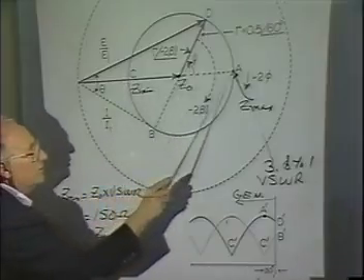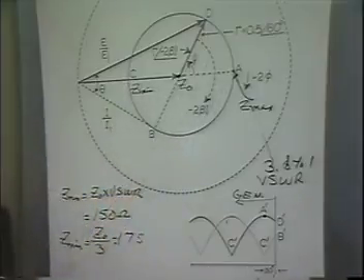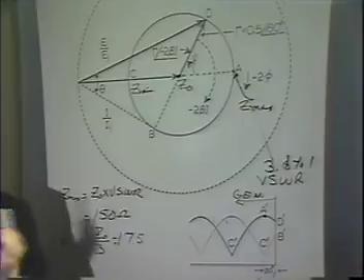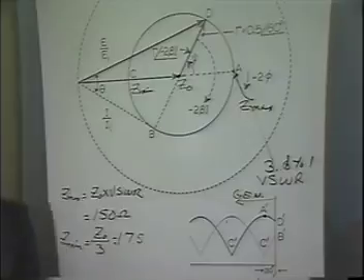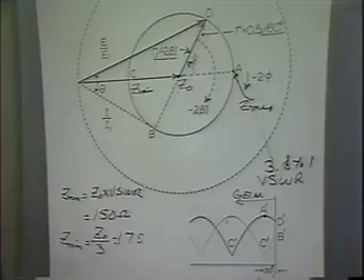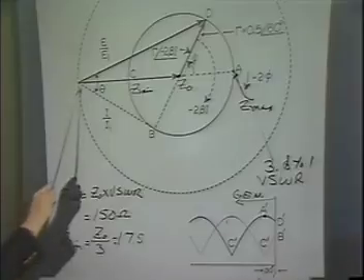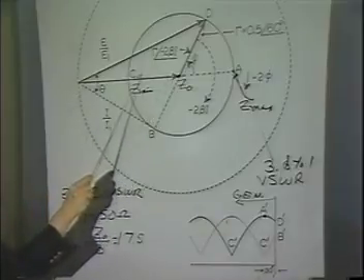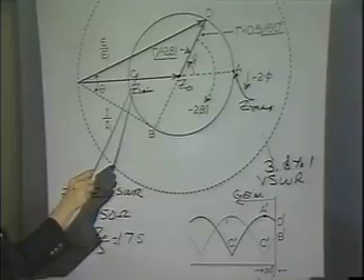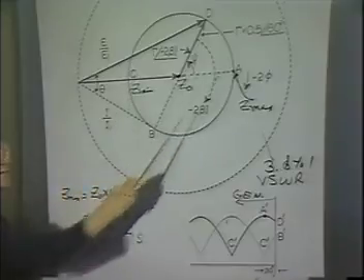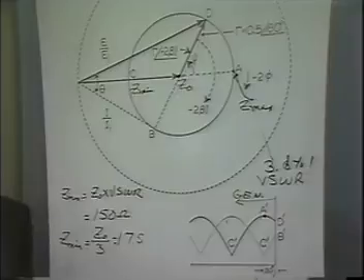Going across the chart over here, Z maximum, pure resistance, greater than Z0. That's the only 2 points on the transmission line then, Z max, Z min, and repeating itself, Z max and Z min. That's the only time you have a pure resistance on the transmission line. Because you see, that's the point where E incident, I incident are in phase, and here the reflected voltage is in phase.